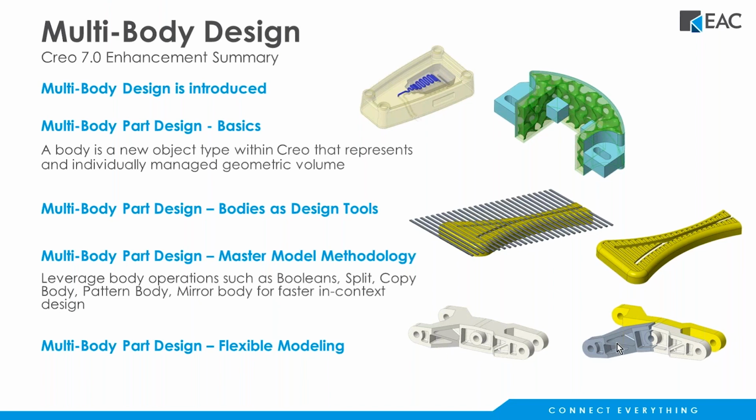And then a final example, we're using flex modeling. Here, whether it's a parametric part or a step file or something like that, you're doing some subtractions. Here's a split. I split this guy down the middle, so now I have two parts. Then I take one of those two parts and split it again in half. Then I rotate half of it. And then I can remerge them together and remerge them with the original one. And now I've got a fully defined part where we've cocked one of the arms off at maybe 15 degrees or whatever. So it's allowing us to dissect and break parts apart and then remerge them together after we've made some changes, should we choose to do that.